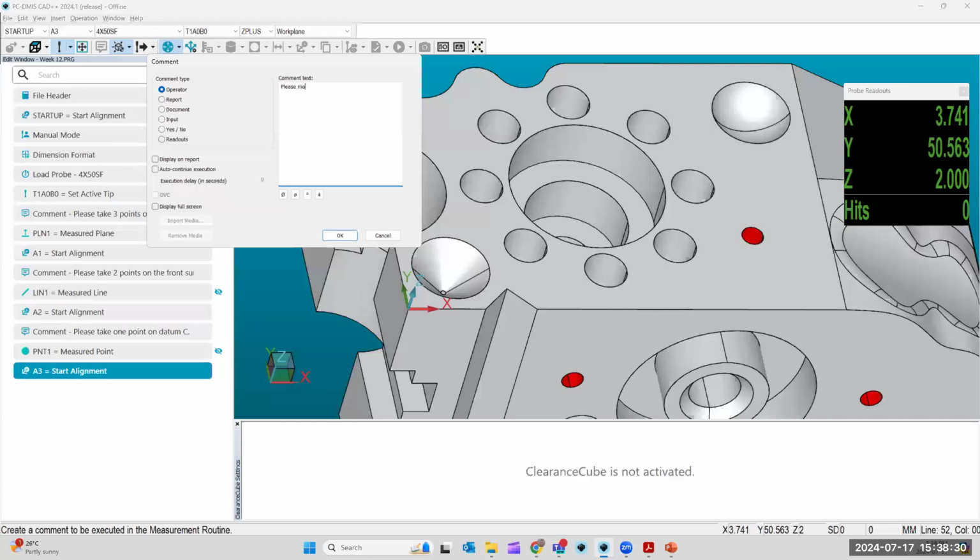Make the probe outside of the clearance cube. Move the probe. Yeah, that's kind of right, but make sure your sentence is nice and clear. You want them to move the tip above the clearance cube. So the operator needs to physically take the joystick in manual mode and move the tip up above the clearance cube before anything activates, before any DCC movements, okay?